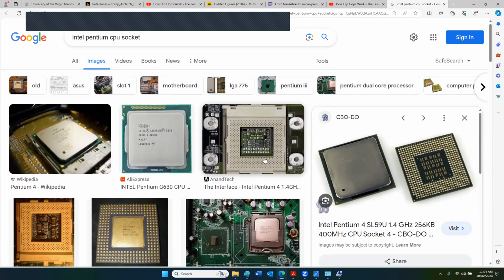And if you don't, it can be turned so that the dot is over here, or over here, or over there. And the problem is that all of these connectors would be out of alignment, right? And actually the CPU wouldn't be able to do its job and it wouldn't function properly. Because there's so much input output on a modern CPU, you have to have a way of guaranteeing the orientation when they're mated with the connectors on the motherboard.